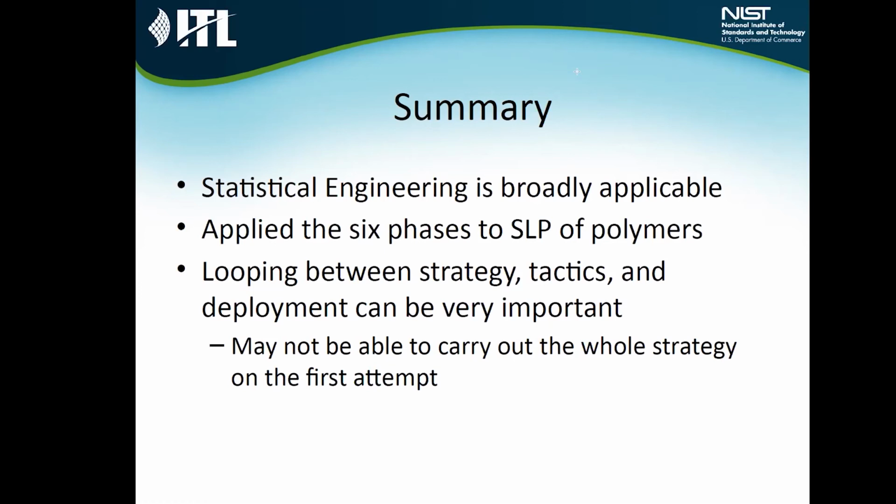Okay, a question: does UV strength change depending on location, meaning degradation may vary? Yes, that's a very good point. UV strength does change, of course. Farther south, you get more intense UV than farther north. But the hope is that by measuring appropriately the amount of UV, the dose of UV, how much UV the sample is actually absorbing, that will account for those differences. We have not tested that at this point, but it's certainly a very good point.